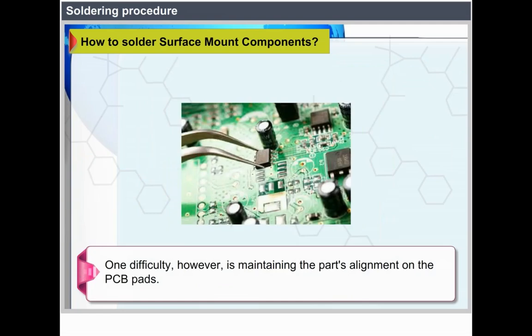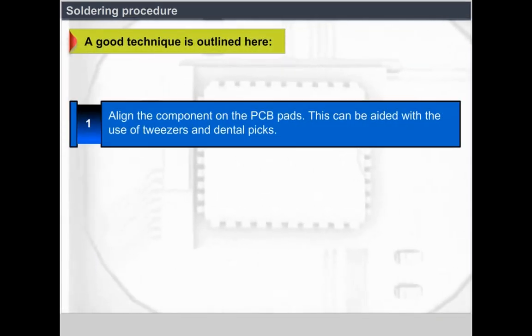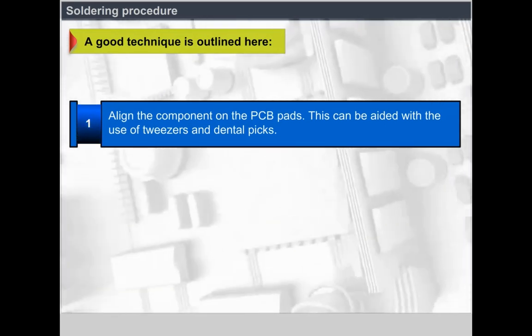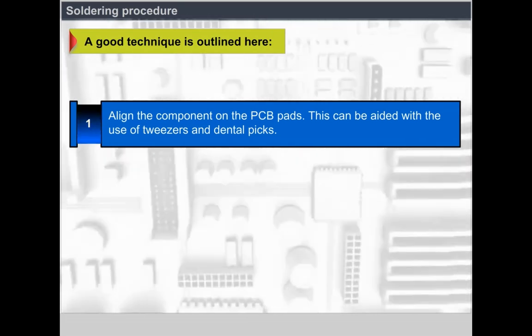One difficulty, however, is maintaining the part's alignment on the PCB pads. A good technique is outlined here. Align the component on the PCB pads. This can be aided with the use of tweezers and dental picks.